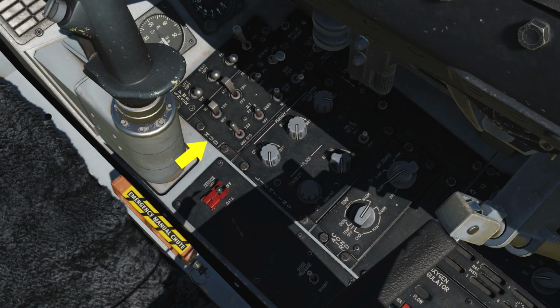As the name implies, the HUD control panel determines how and what information is displayed to the heads-up display. The panel consists of 8 switches. First is the scale switch. When set to VV/VAH, the vertical velocity scale, altitude scale, and the heading tape are displayed. When set to VAH, all the scales are displayed except for the vertical velocity scale. Off removes all scales but the digital readouts.